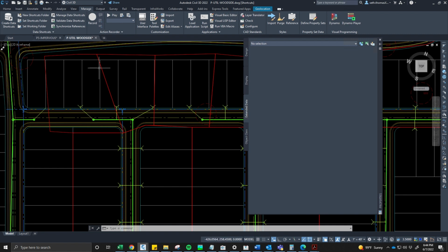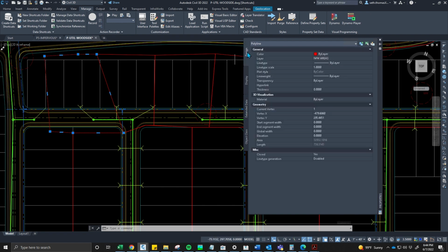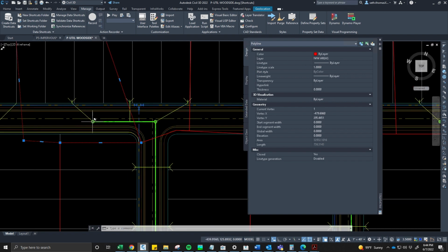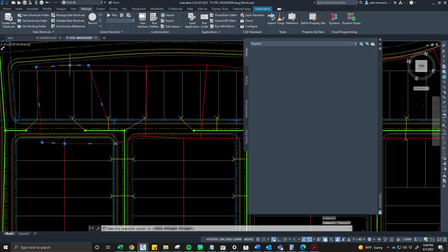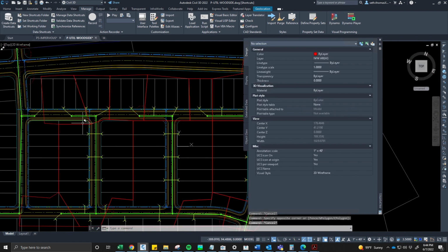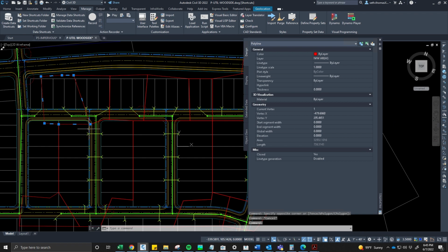The wastewater flow calculator does this by associating a closed polyline on the layer wastewater areas with an exclamation point in front of it, and detects the manholes within it. One area should have a single manhole in it, and it will enter that data, or the area of this line, into our spreadsheet for us.